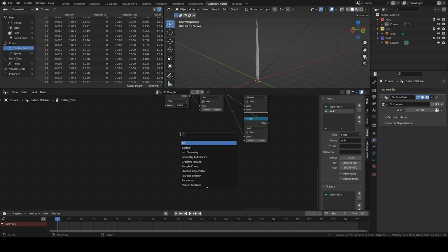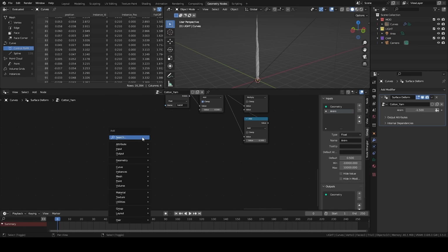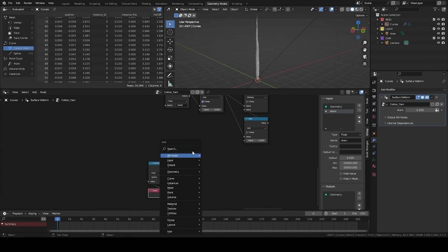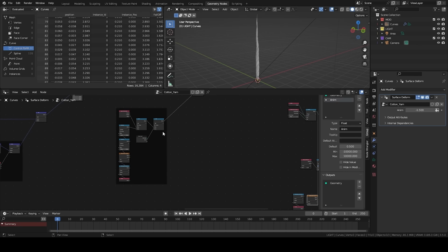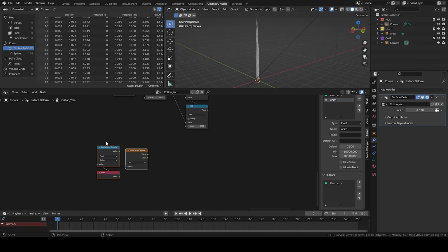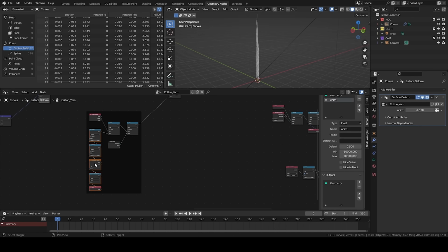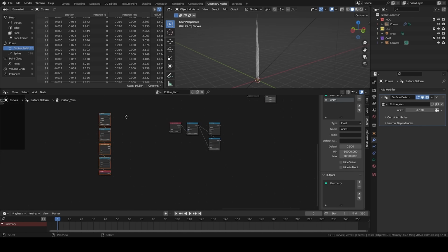There, I'm going to create an index node. Once again, evaluate on domain. I'm working on splines this time. I'm going to create a white noise node like we had built just before. That little hierarchy, we can even recover from elsewhere. We do Shift-D, Alt-P to get out of the block. And I'm going to plug in there.